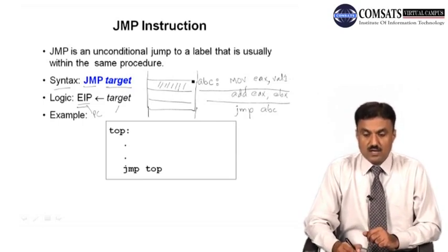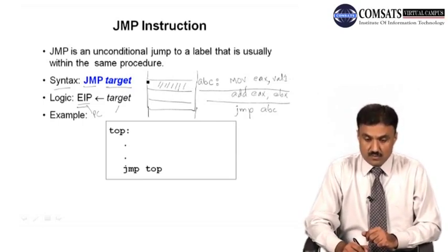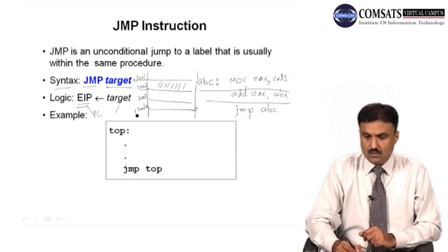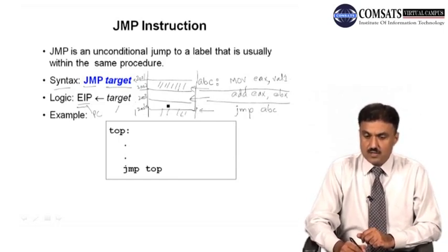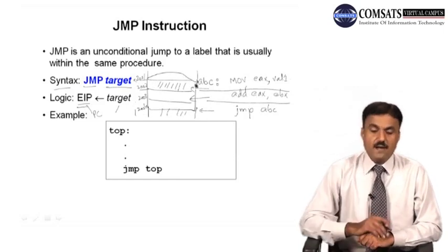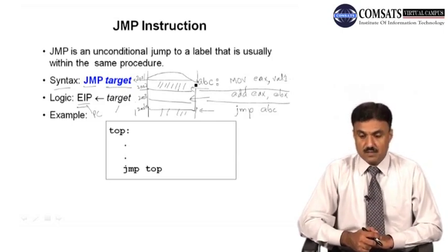So, for example, whether these are 1-byte or 2-byte instructions, there should be a starting address, like 2001, 2002, 2003, 2004, and so on. This one is a one-byte instruction, and this one is a multiple-byte instruction, for example. So this starting address is identified by this label ABC.